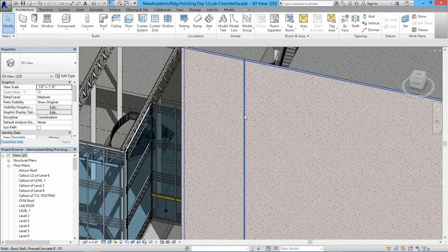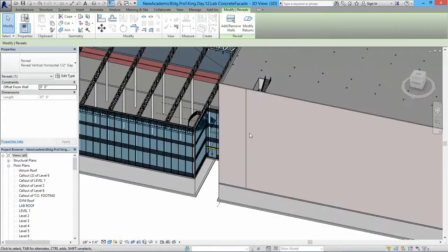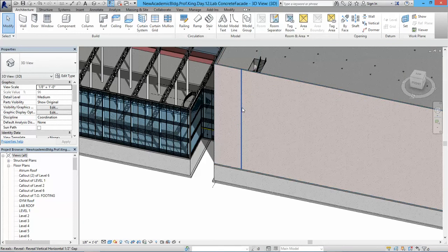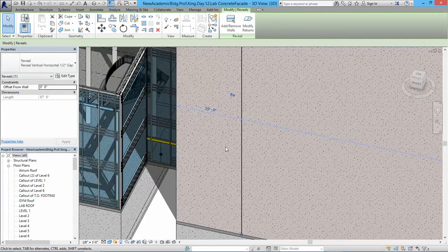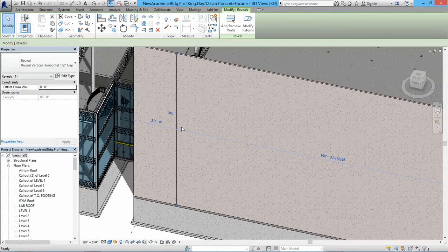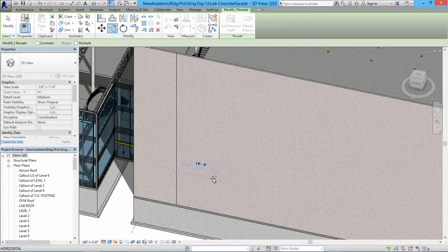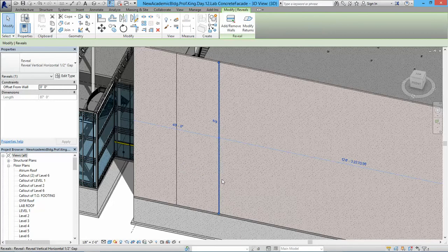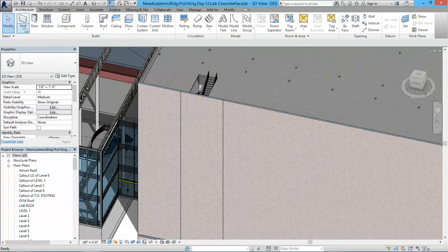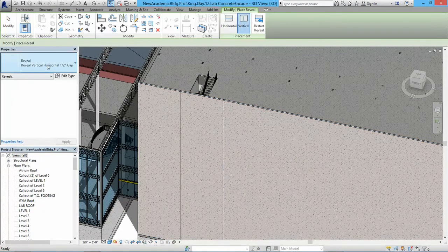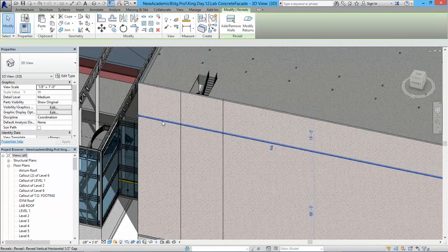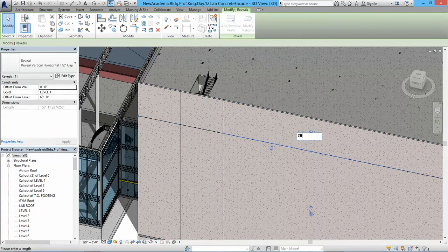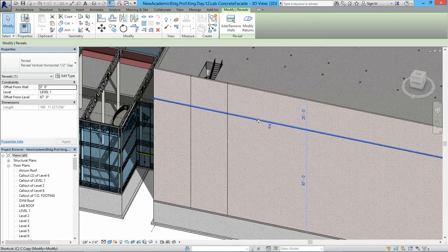You can also be more specific about the dimensions and copy them. For example, tab, you see there's dimensions. You can say give me 20, so it moves exactly 20. You can say CO as in copying, and again say 20. And you can also say obviously wall, rebuild. It stays there. Remember the last one, and press horizontal here, and the same way. You can tab into that element, say 20 or whatever dimension, CO.